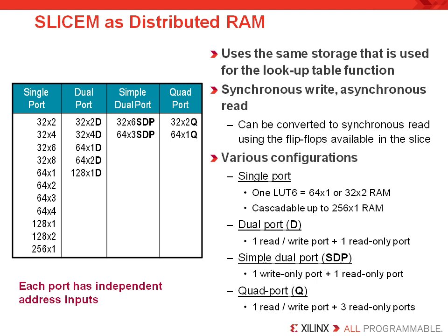Sometimes customers try to build larger memories out of these, but it is important to keep in mind that the extra logic used to connect them together will make the performance prohibitive. So only do it if you don't care about the speed of the memory. And in general, those customers that build with this are using the core generator or system generator to build a DSP application. Also keep in mind that if you're trying to build a larger memory, it might be better to actually target the block RAM resources that are dedicated to silicon, and that is usually easily instantiated from the core generator.